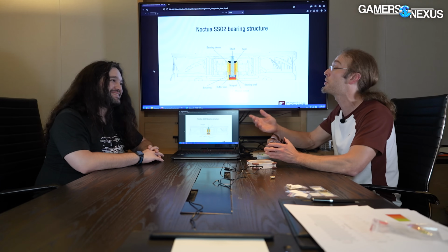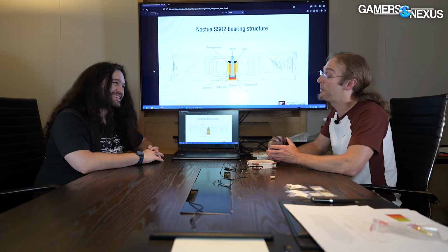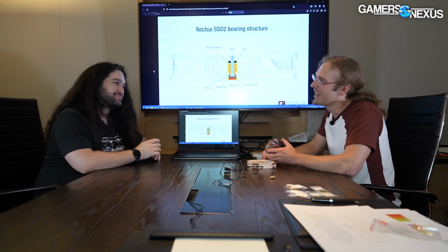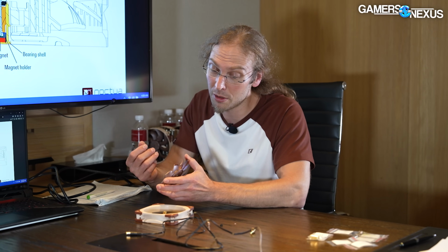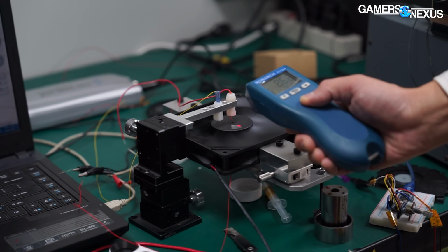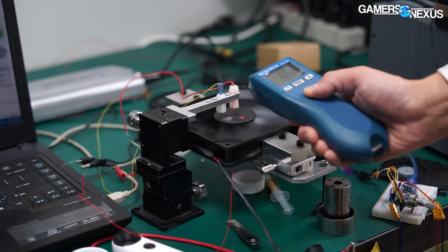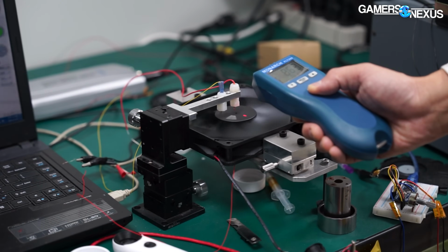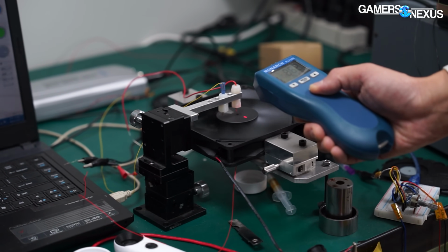So why don't you use ball bearings on all fans? They are superior, right? But they have acoustic penalties. They are louder in the beginning already. You can always hear those balls moving, and once the balls start to wear, they get even louder. So you only want to use that if necessary. And similar arguments could be made with regards to FDB, like grooved sleeve bearings.